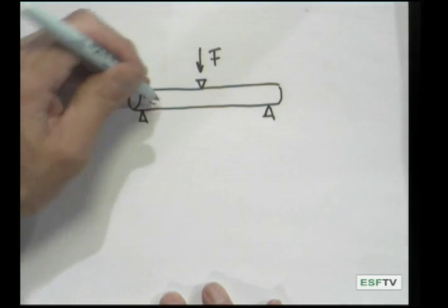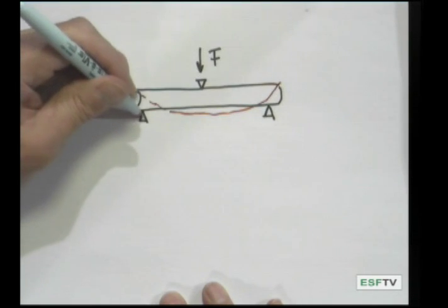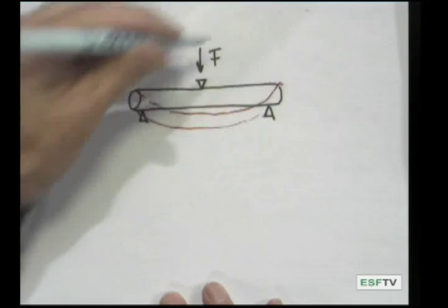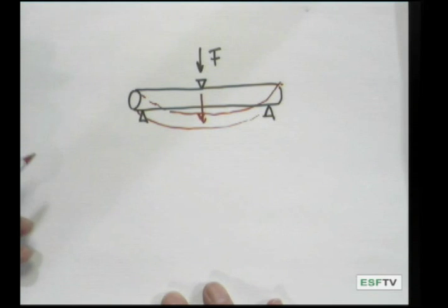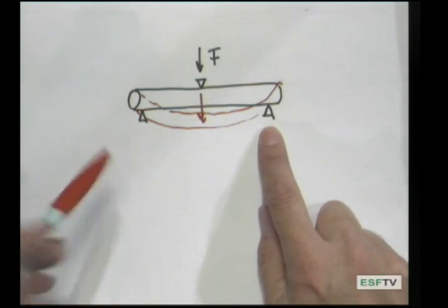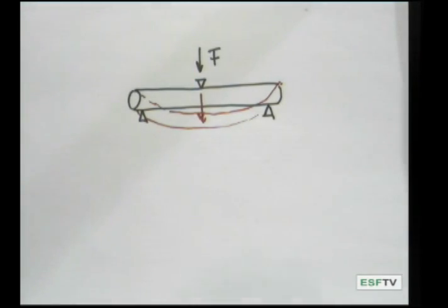And this is going to be exaggerated quite a bit. The deformation will operate this way. That is, you'll be pushing down on the bone like this, and the bone will bend between those 3 points: 2 points of resistance and 1 point where you're applying a force. The kind of deformation that you get in that kind of a three-point test is called flexion. And one of the important properties we need to know is something called flexural stiffness.